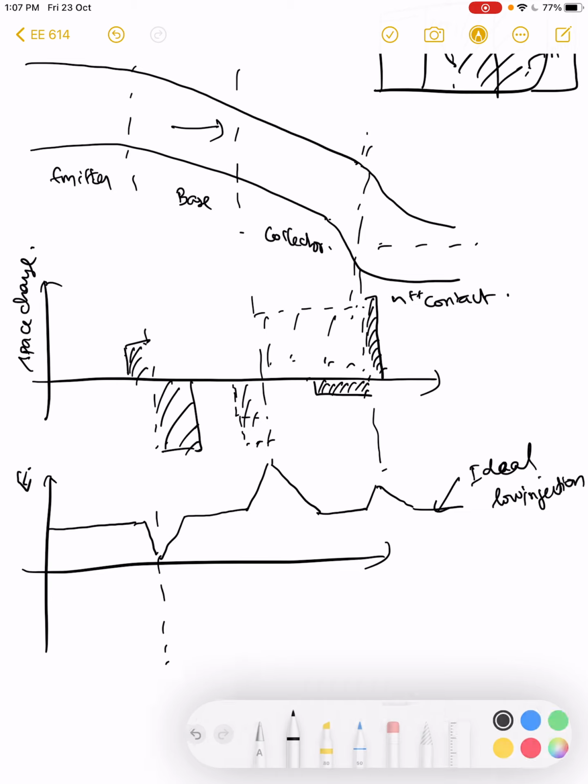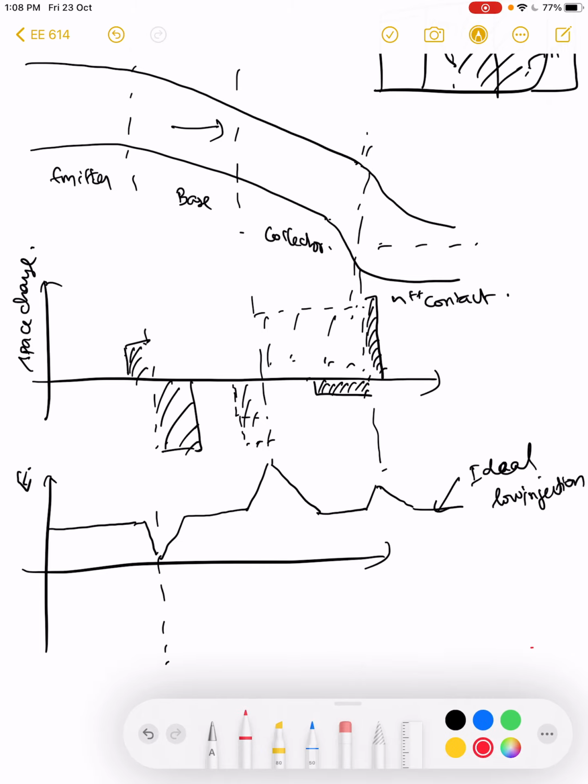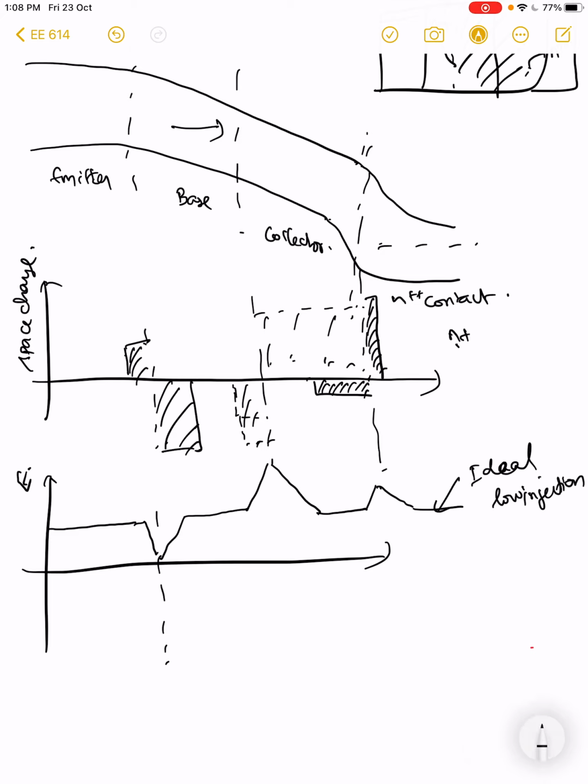Now if I have a very high injection and a very large amount of charge density in the base collector junction, see, how did we get these charges here? The reason we got these charges is we wrote the charge neutrality situation, that is n plus Na minus equal to p plus Nd plus, sorry, right? So this is the actual charge neutrality situation. And we always took the ionized dopant charges to contribute more than the free flowing charges, because we always talked about low injection in the PN junction we spoke about before.